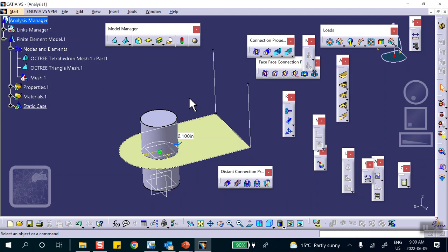If you don't know that step, the difference is that either you can finish the problem or you can't. If you do it in sketch, you must join it. Totally useless, but you must join it. Not so in wireframe. You don't have to join that line. But if you did it in sketch, you had to go join it. Otherwise, you're done for the problem. Pretty much. Can't do the rest of it. I don't have to do that because I drew it in a wireframe.